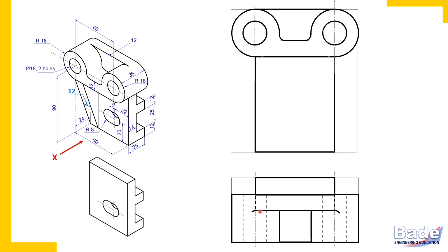Okay, now smaller details. Let's continue with the smaller details. A corner is formed by three edges. Here, from each of these corners, watch these corners. There are edges you can see running from right side to left side. Watch here, these edges are running from right side to left side. So right side to left side, that is parallel to length. So we are going to draw those edges here.